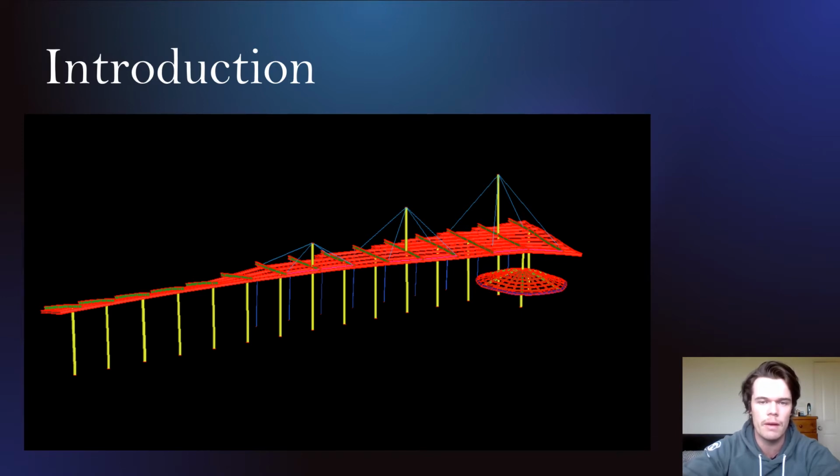It should be noted that finite element software does not account for plastic failure in its computations, and so the deflection results may not be realistic. The user needs to be vigilant when analyzing results for this reason, and verifying results produced by Strand 7 is good engineering practice.